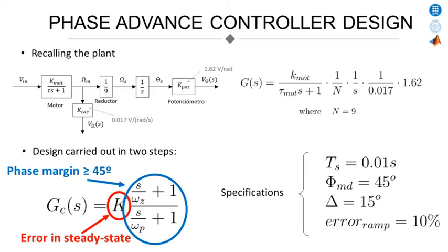For that, two steps are followed. First, the controller gain will be obtained, and after that the maximum phase advance provided by the controller and the length of it is calculated. Finally, the controller is constructed and whether the correction of the obtained new phase margin is checked.